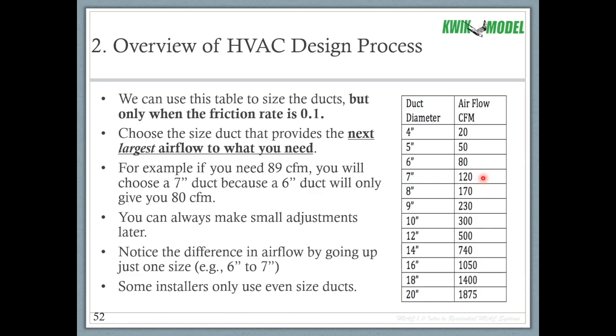Every system I've ever designed, when we went out and actually tested, it moved more air than what we designed it for. If we designed it for 400 CFM per ton, when we turned on that system and went out to commission it and measure the airflow, it always moved more air than the 400 CFM per ton. And that's why: ducts only come in certain sizes, and unless ducts came in increments of tenths of an inch, there's some extra built-in capacity, and it's substantial.